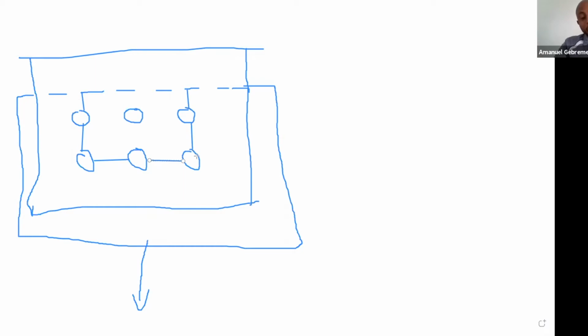That is called a shear block failure limit state, where a portion of the plate is failing in tension. And these are these two lines here, and maybe I should draw them with a thicker line. There. And then my two thin lines are failing in shear.